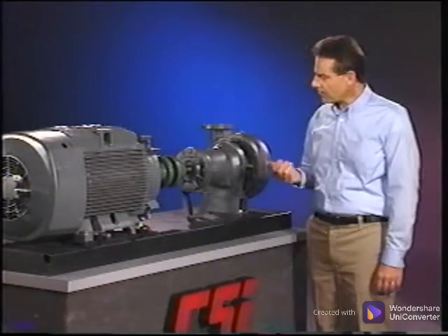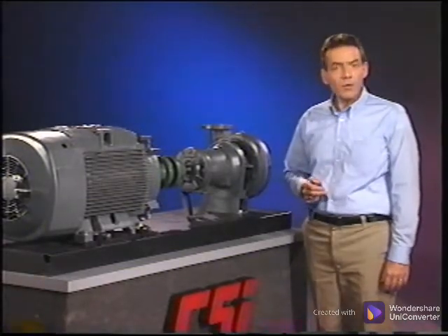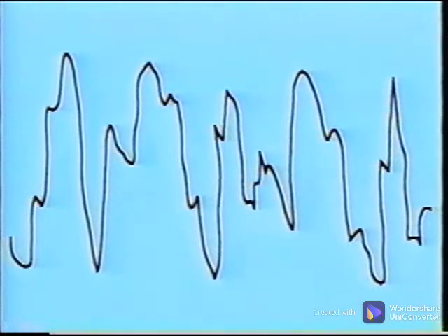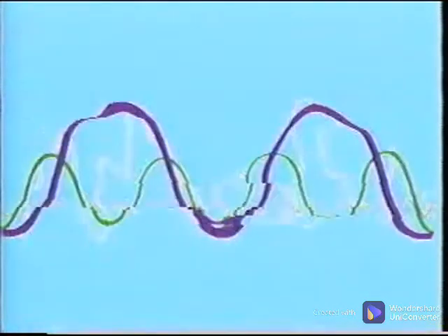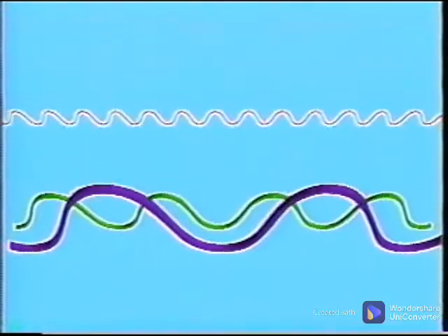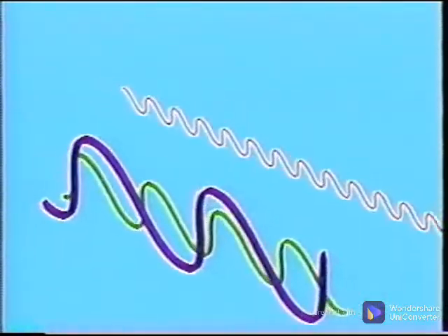If this data was from a pump, a peak could show up which would equal the number of vanes on the impeller. The waveform here is more complex because of the added energy. Now during one rotation of the shaft, 7 complete cycles are generated. Again, the processing separates the waveform into individual sine waves. The calculations are made which convert this data into a spectrum.